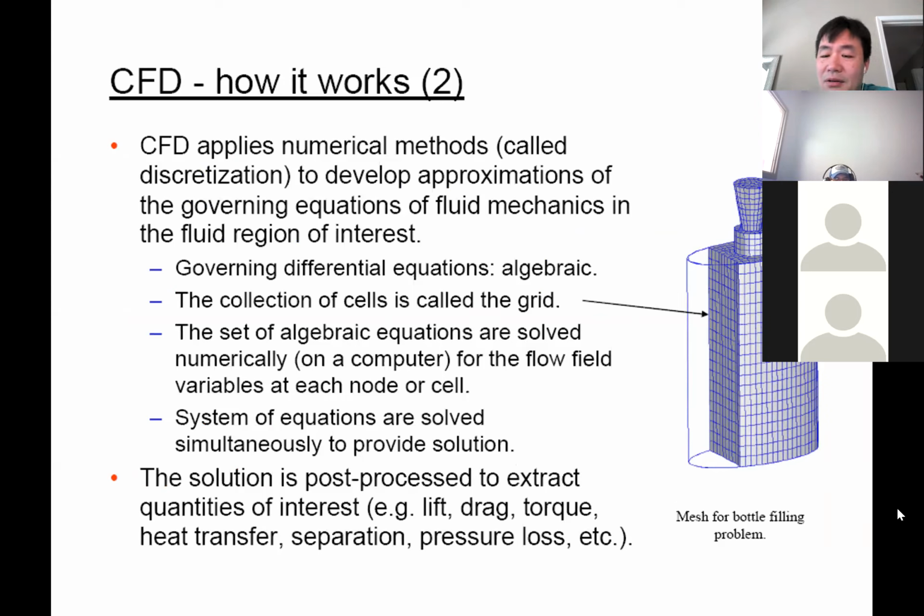You can pick a location as if you have a sensor in that location, and let Fluent plot the change of this value at that location versus time. XY plot: X could be the time, Y could be the value. So it will show the change of the value in terms of time.